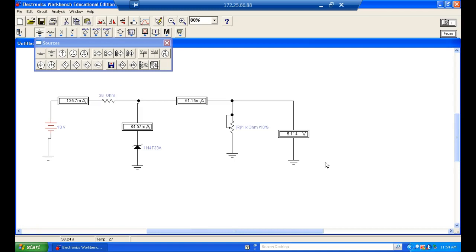So this guy is dynamic, right? You understand. It's sitting there doing what? Constantly varying its resistance, trying to maintain a constant voltage across its leads. So normally we put the guy in there what? Reverse bias, right? Everybody understand that. That's when it's regulated. Reverse bias. If I hook it up forward bias, what's going to happen?